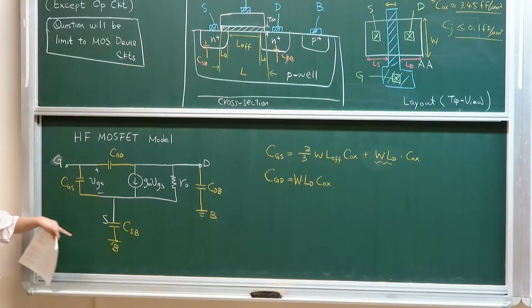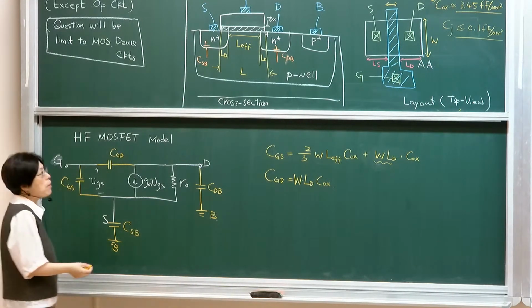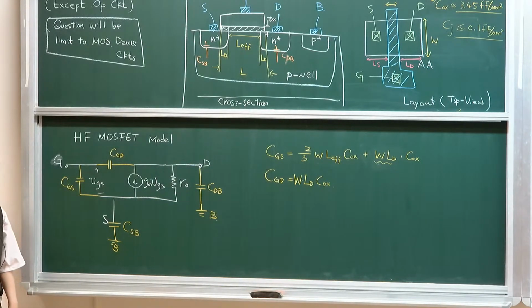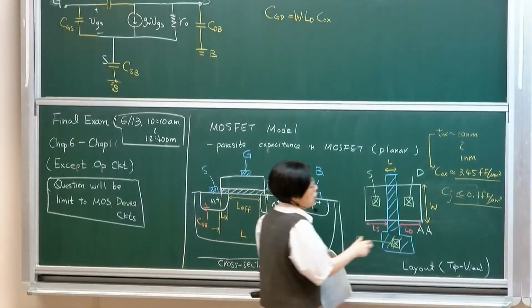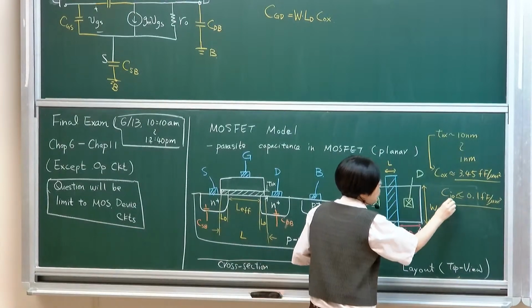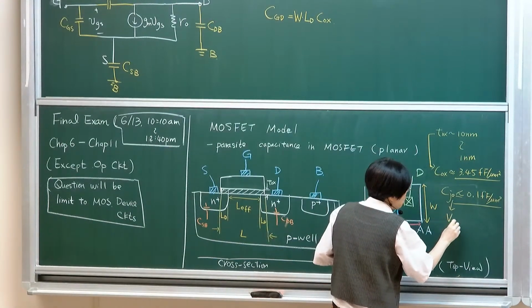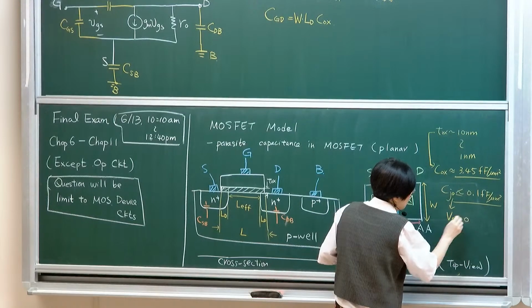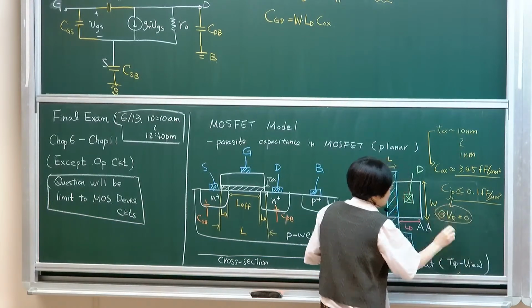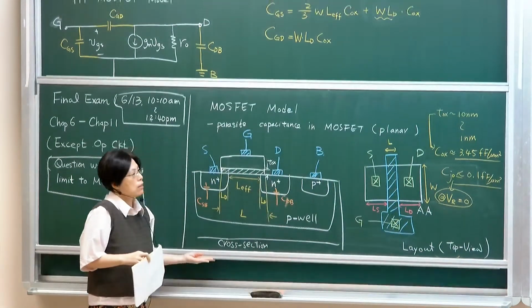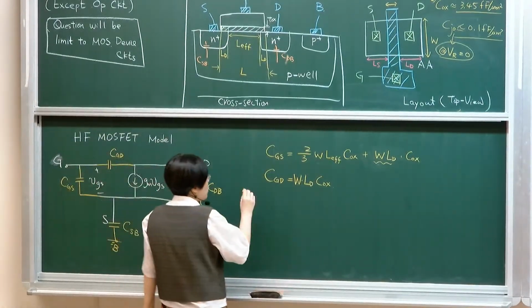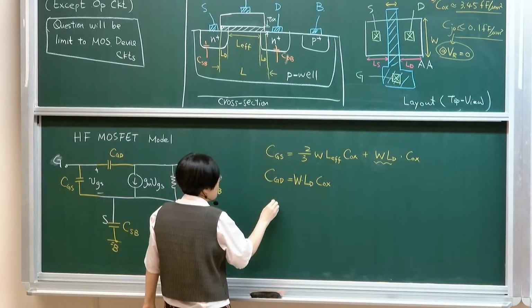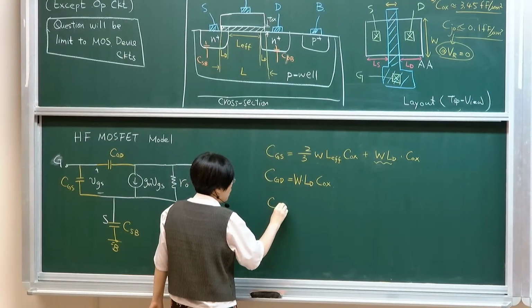And then I did not discuss the junction capacitance. Typically, what you will be given in most of the models is also junction capacitance like this. Unit area junction capacitance, CJ0, simply means that you assume the bias voltage is at 0. So your junction capacitance, of course, we're adding some biasing dependency, but what happens is that you can determine your junction capacitance, CSB.